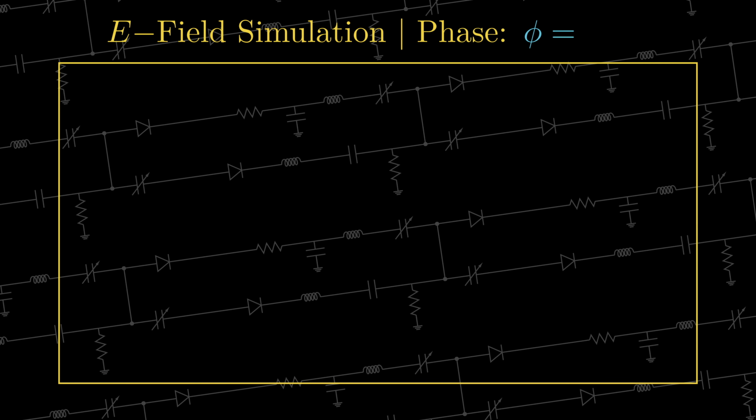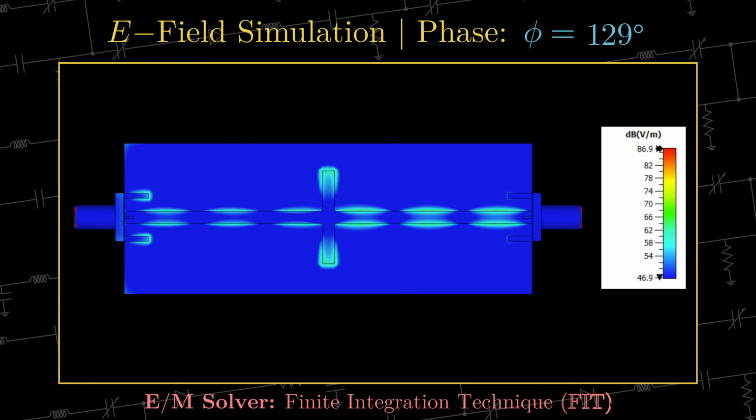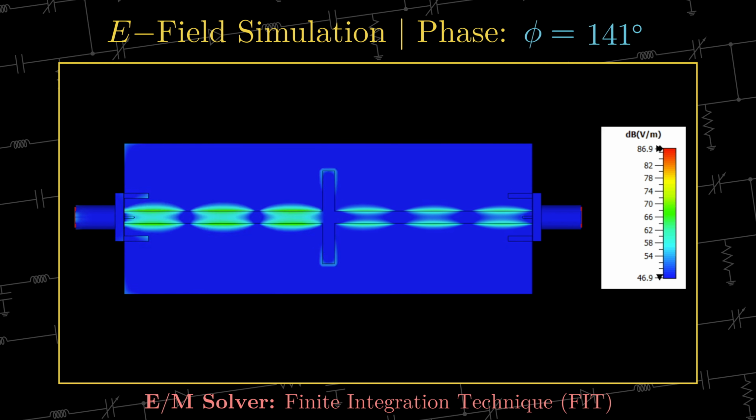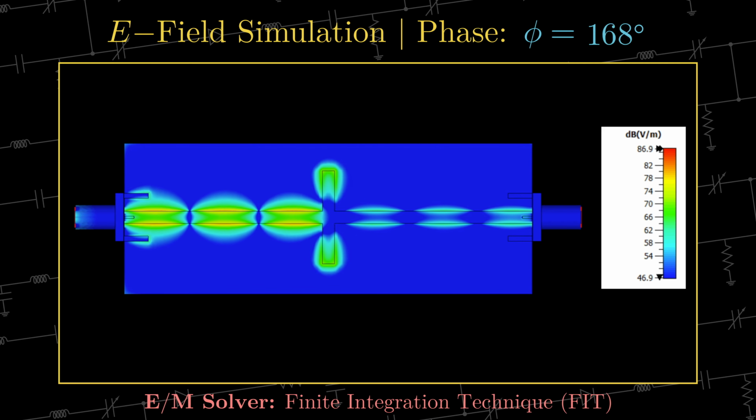If we head back to the E-field visualization, it is obvious that the introduction of an intervening trace, representing an impedance mismatch, reflects a significant amount of energy back to the incident port, while considerably attenuating the amount of energy transmitted to the output port. But why does the energy on the left appear to oscillate instead of simply traveling backwards?